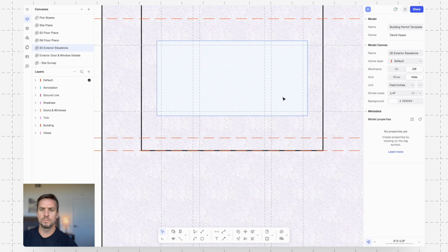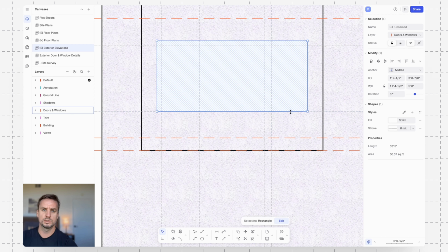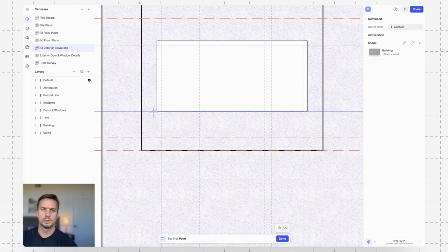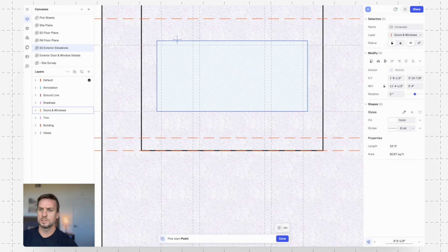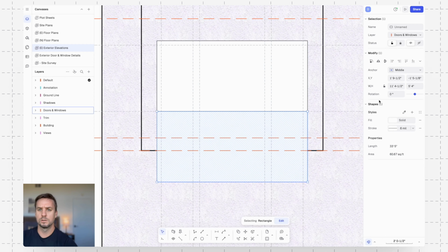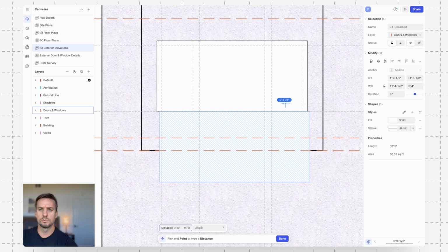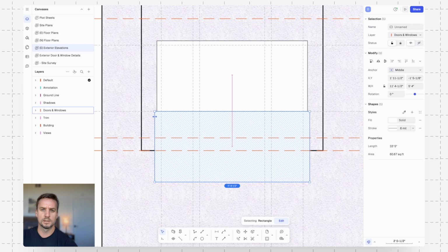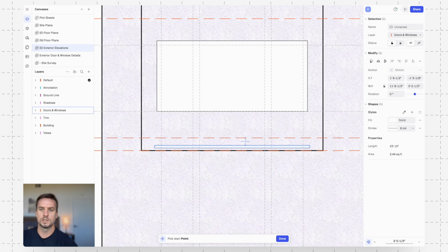So there I've got the frame, and I actually know that I'm going to add an extra sill in here, so maybe I'll do that first. Actually, kind of an easy thing to do is I can just copy this down, and maybe I want this to hang over by 2 inches. And then once I have one side set, it's automatically gonna snap to have this aligned, so it'll be really easy to bring that out on the other side as well. Height, maybe I want this to be just like 2.5 inches. And it's gonna put it in the center, so all I have to do is then just drag it up.